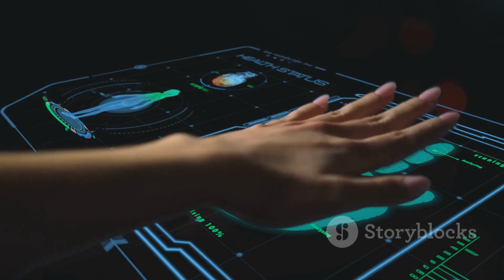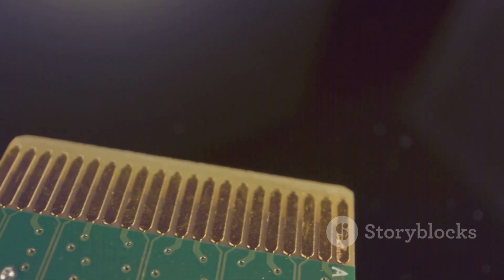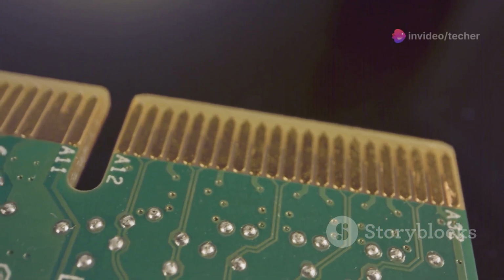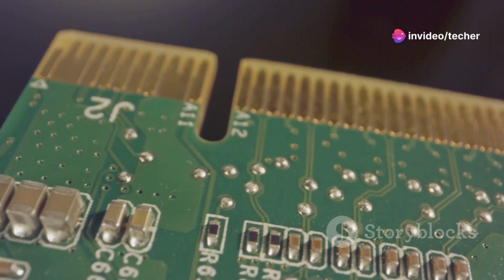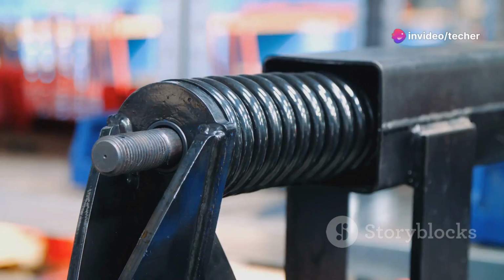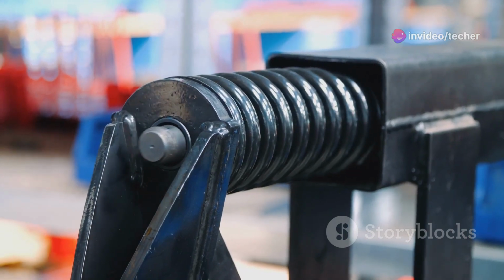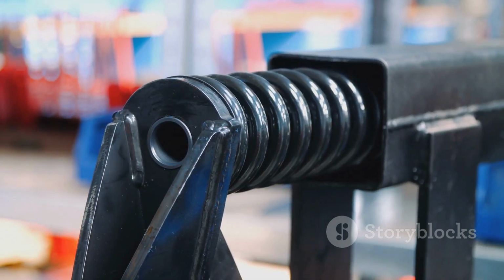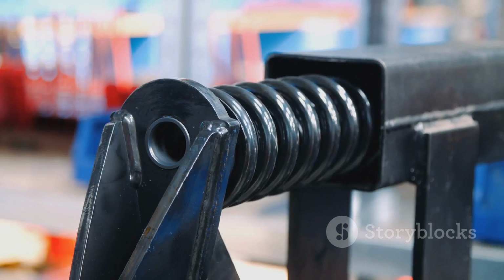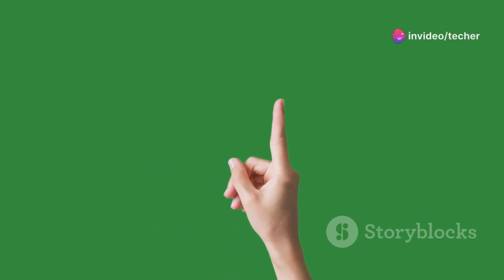perfect for touch-sensitive applications. These sensors are composed of 2 layers of conductive material, separated by a thin, compressible spacer. When force is applied to the surface of an FSR, the spacer compresses, which brings the conductive layers closer together. This action reduces the resistance between the layers, leading to a measurable change in electrical conductivity.